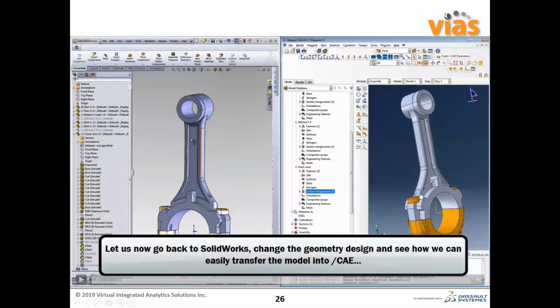You really can't capture those frictional contacts or the highly nonlinear contact behavior using SolidWorks Simulation. SolidWorks will be able to do it to a certain extent, but it will struggle a lot to solve this kind of problem. Abaqus is well known for solving this kind of advanced contact problem.